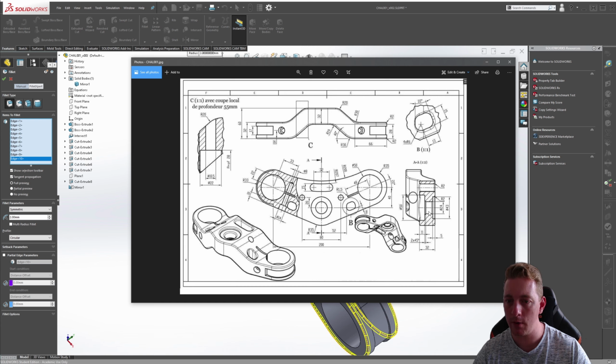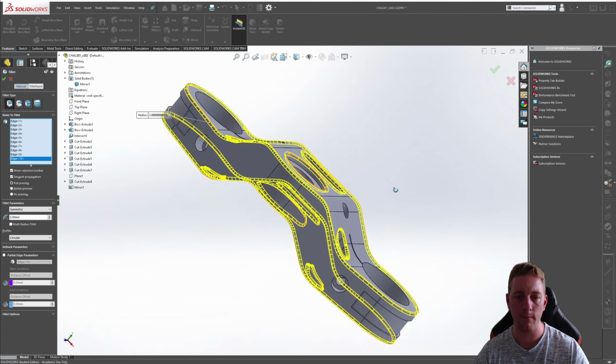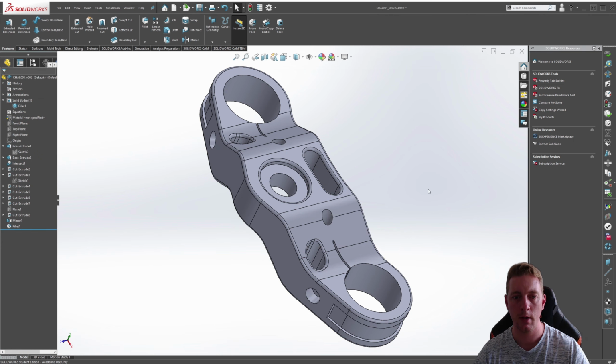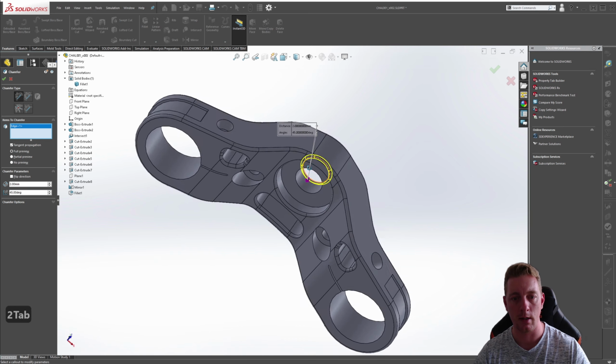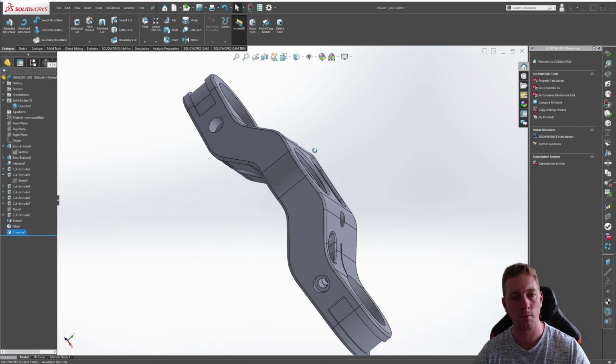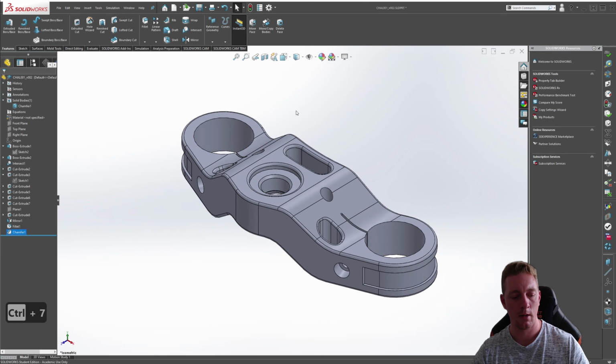There is more on the inside edge here, but they are actually chamfers instead of fillets. It's pointed out in one area. I'm just trying to find it. Okay, over here, 2 times 45. So that means it's a chamfer of 2 millimeters at a 45 degree. So we do our fillets first, pick all those, and then we want to do the chamfer. Make sure it is 2 mils, 45 degrees, and we pick this edge and this edge. And there we go. And that's it.